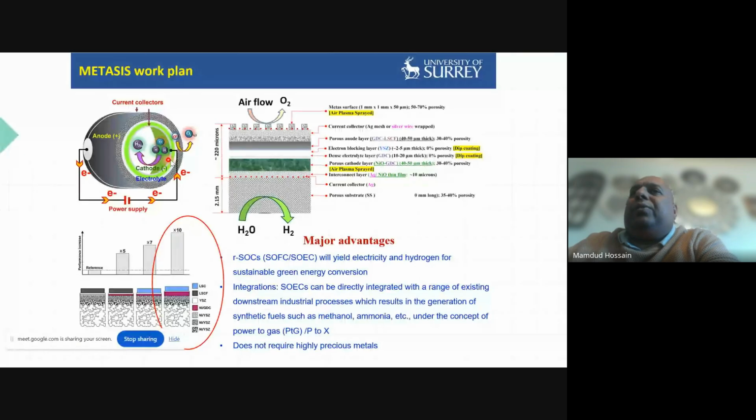So inside this tube, we have steam at a high temperature flowing through this tube. That steam is split into hydrogen and oxygen. What happens is that we apply electron into that steam, which splits this atom. So we end up with electron going into oxygen and turning into oxygen ion, oxygen minus 2. It's taking 2 electron from this circuit. And hydrogen combined together producing hydrogen gas. So we have hydrogen gas in cathode as well as steam.